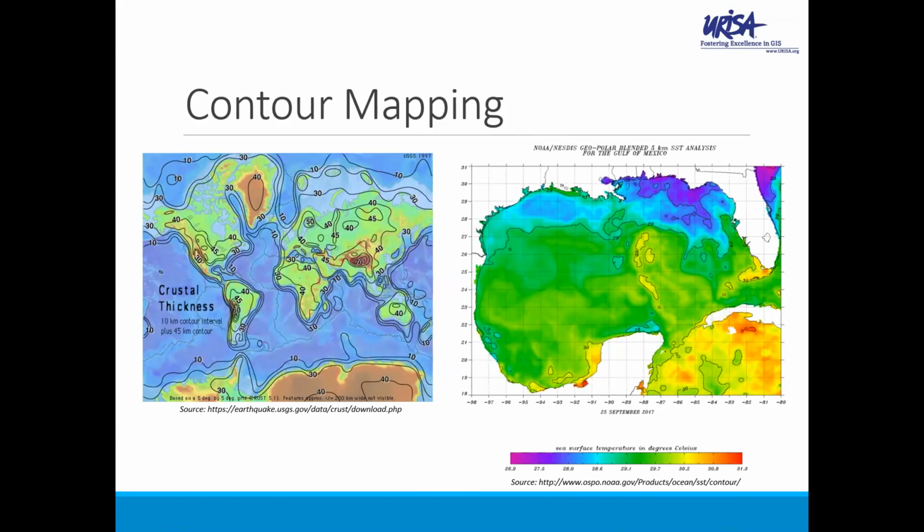What do the closed lines, the ellipses or circles on a contour map, indicate to you? Usually that's a hill or a peak. But if it's hatched inward, you need to remember that that indicates a decrease in value. Label placement is another key element to understanding good contour mapping. If you place a label on top of a line, sometimes it's really difficult to read that label if you don't eliminate the line running through the label. You need diligent placement, and remember to adjust those labels if necessary.